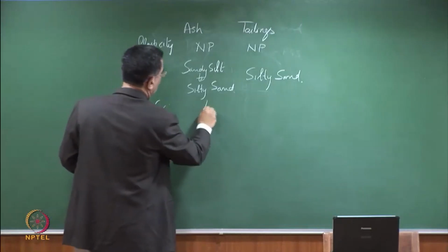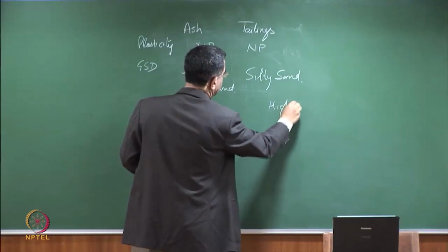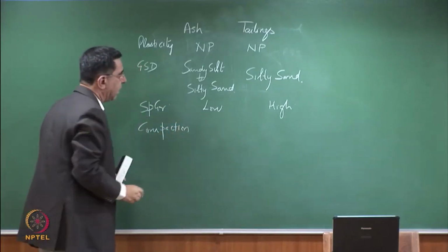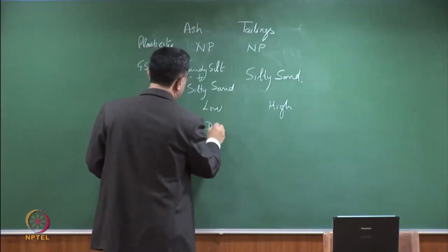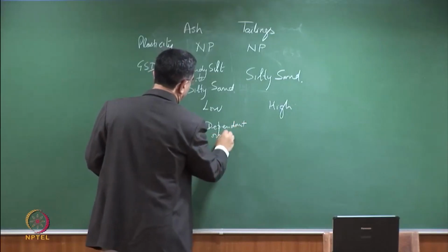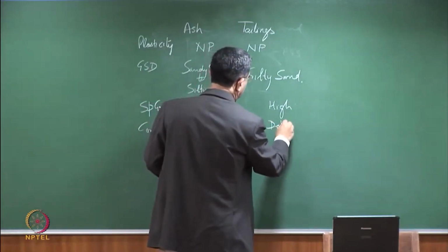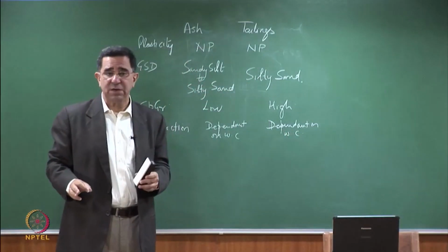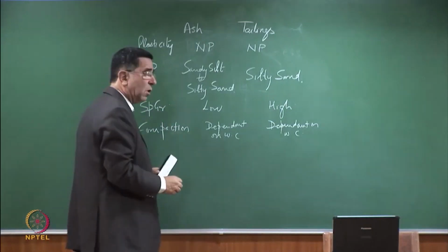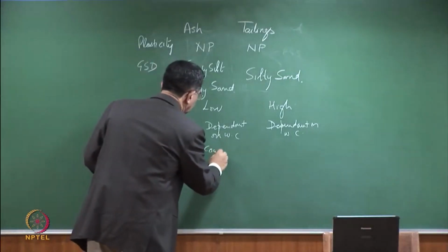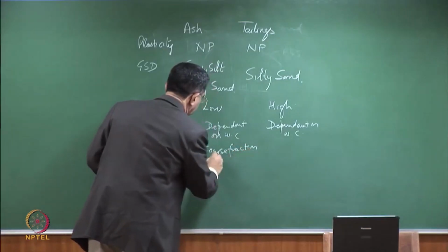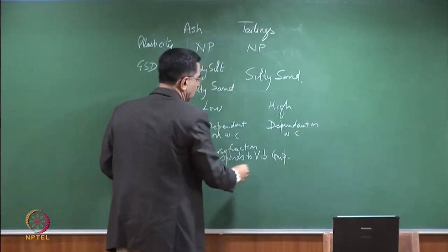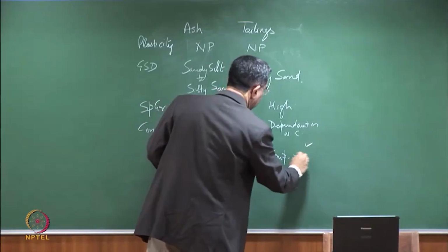Specific gravity, low in comparison to soils, high in comparison to soils. Compaction, usually there is an OMC, dependent on water content. But in both cases, the coarse fraction responds well to vibratory compaction. This is the same for both.